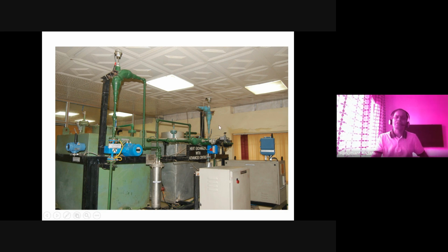Temperature is measured because in a heat exchanger, suppose the hot water inlet is at ambient temperature, say 30 degrees, you will get a higher temperature when you measure the output. You can see this is the input side measurement, and the output measurement is somewhere on the other side. You can see a small pipeline coming from here. It is a tube side measurement. So you can have a tube and shell type of heat exchanger here.